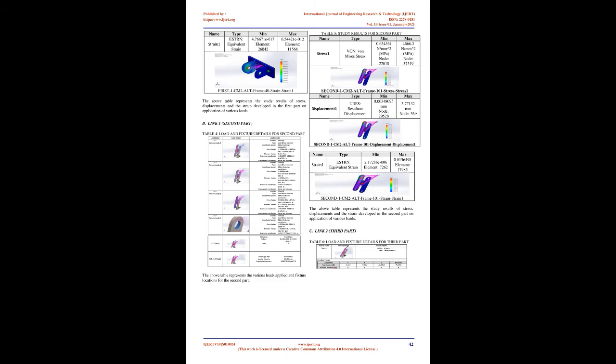Building a model basically starts by drawing a 2D sketch which consists of geometry such as points, lines, arcs, conics and splines. Dimensions are added to the sketch to define the size and location of the geometry. Relations define attributes like perpendicularity, tangency, parallelism, and concentricity. The parametric nature implies that the size and relations drive the geometry, not the opposite way around. The dimensions within the sketch are often controlled independently, or by relationships to other parameters inside or outside of the sketch. SolidWorks also includes advanced mating features.